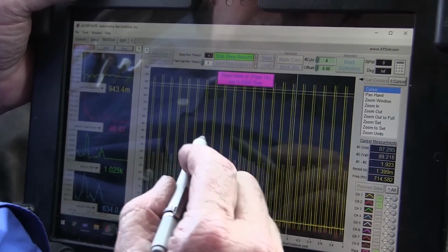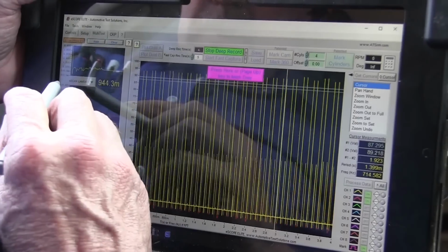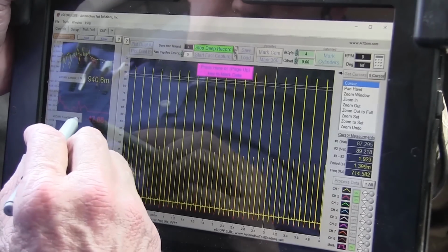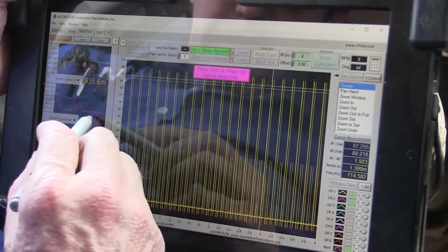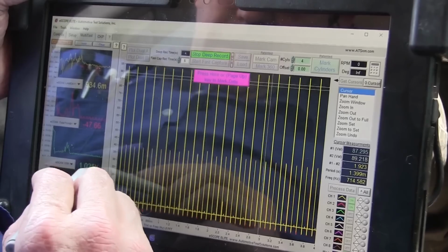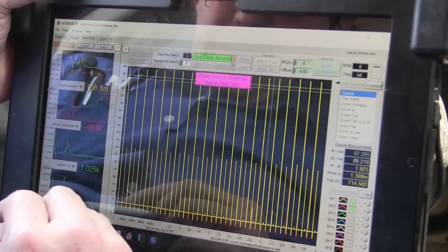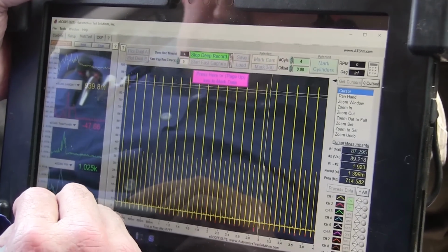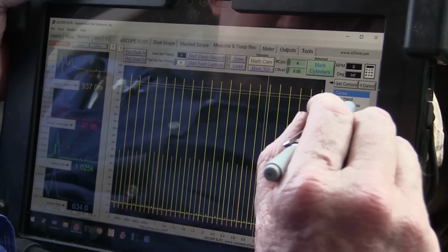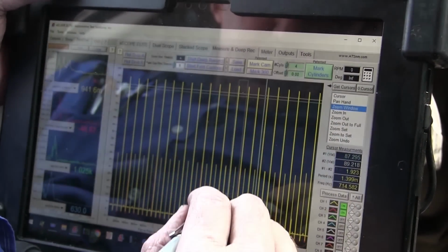Okay guys, so this is my number 2 injector. This is my Lambda and we're a little rich right now and I'm taking away 47% trim. The fuel pressure is, divide that by 2, so I got about 500 pounds and we got an idle at 620, 30 RPM.